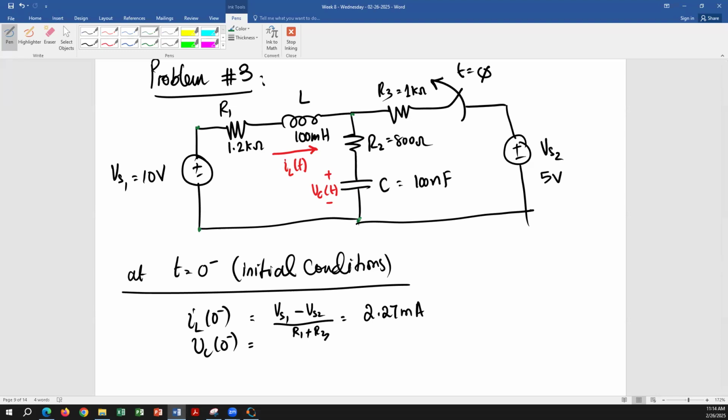Why do you want to say that they're parallel with each other? Yes, Natasha. Vs1 minus Vs2 is Vc. No, it's not. Okay, anyone else? Exactly right. Vs1 minus the voltage drop here is the voltage right here. Vs1 is here, Vs2 is here. When you subtract these two, how is this going to be equal to this voltage? They're not.